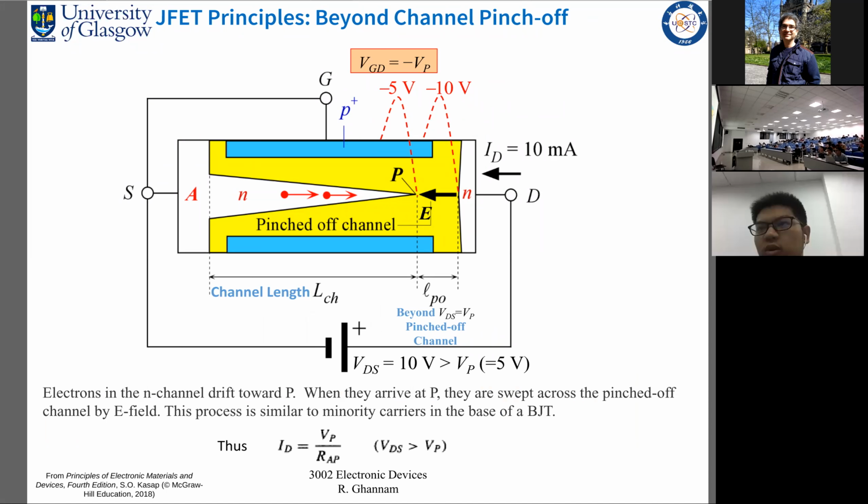So here are some further explanations to what happens just beyond pinch-off. So that means when VGS is much greater than the pinch-off voltage VP.